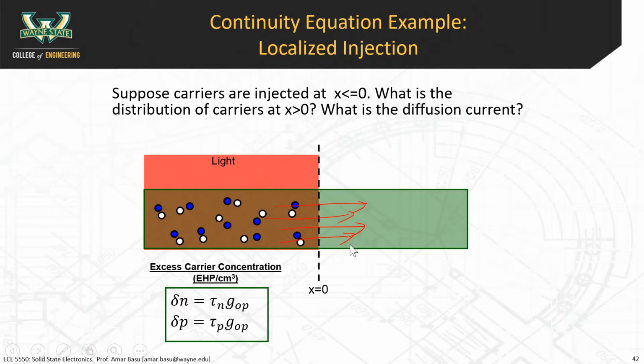You're injecting all these excess carriers, and because the carrier concentrations are larger due to this excess injection, there's going to be more recombination happening here. Think about a carrier being generated on the left side, and then diffusing over to the right, but within a very small amount of time, they recombine. So this gets us now to our definition of diffusion length.